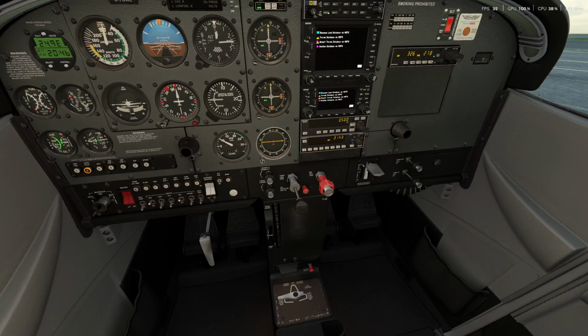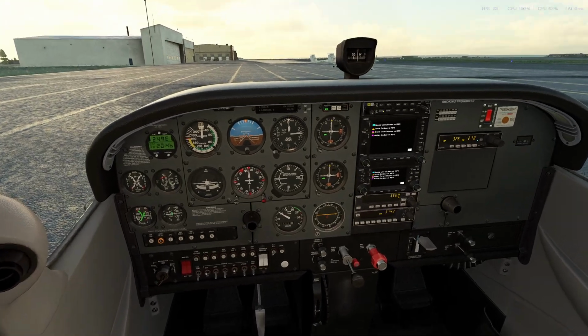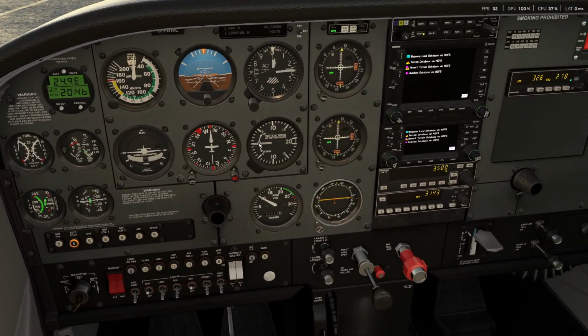When you actually do that, a lot of the times, especially in the real airplane, the vertical speed will kind of flicker. The reason is because the inside cabin temperature is typically different than the external ambient temperature, and those pressure differences will make the vertical speed indicator fluctuate.